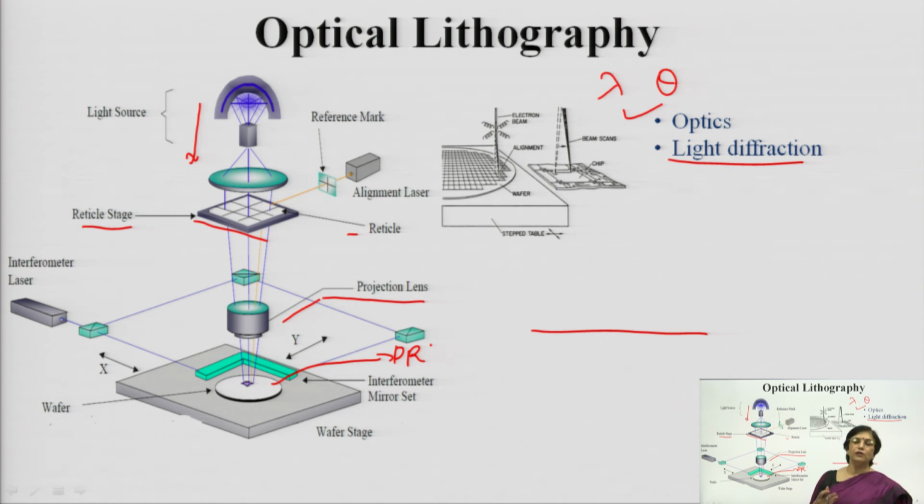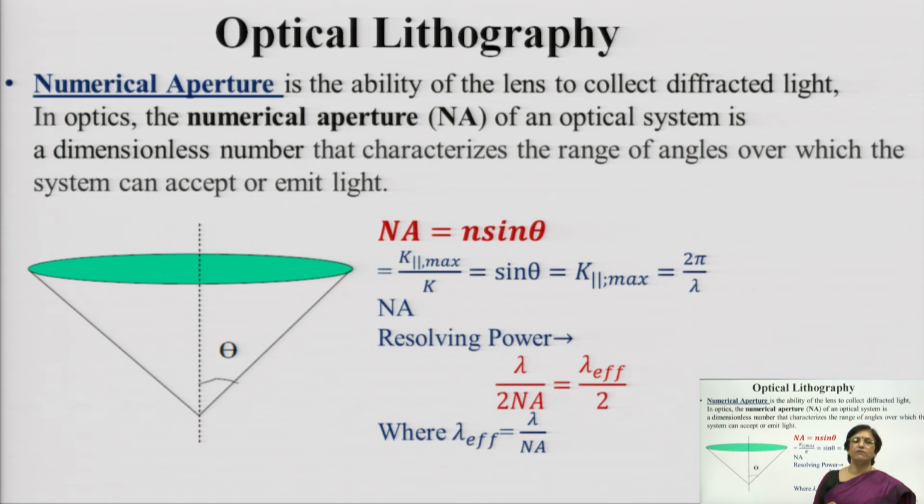So, you need to ensure that the coating is even, therefore you carry out the soft bake also, just to ensure that the pinholes are covered and you have uniform coating of PR onto the wafer surface. So, you have a stable table on which the wafer will be placed, you have exact alignment using these reticles, the electron beam will be focused, and you will have this beam scan being done using the light source, and the pattern will be transferred.